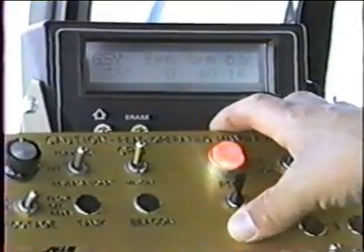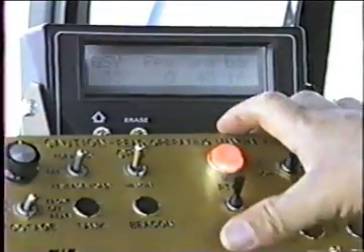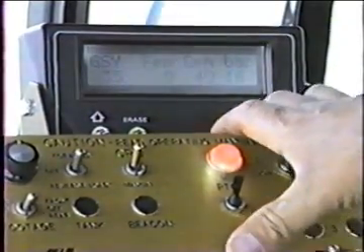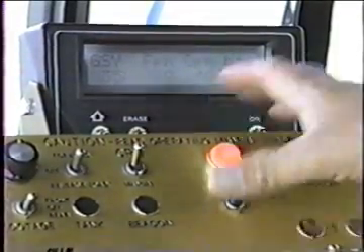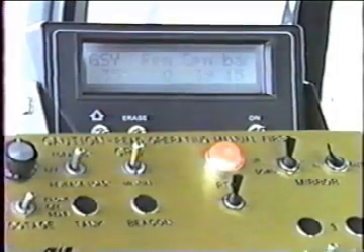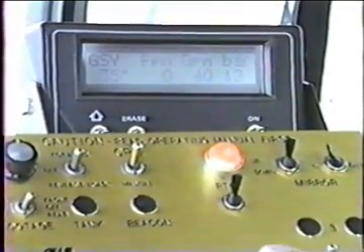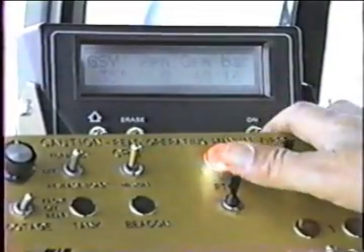Once we have set the idle position, we only have to do it again if we want to change the idle number. Idle is set at 40, the pump is idling at 40 gallons a minute. The computer sees 16 feet of spray bar. It sees whatever switches are turned on. If we turn on or off the switches, it changes the bar width.